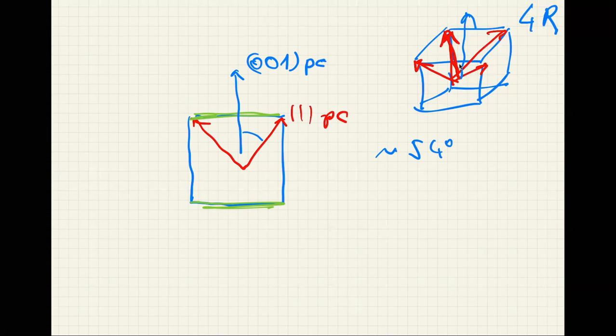You can read this paper by Wada and Tsurumi that I recommended before, from the end of the 1990s or beginning of 2000. Only under those conditions will these materials not give you hysteresis. And they give you also a very, very large response, because this d33 coefficient uses this polarization rotation at morphotropic phase boundary compositions.